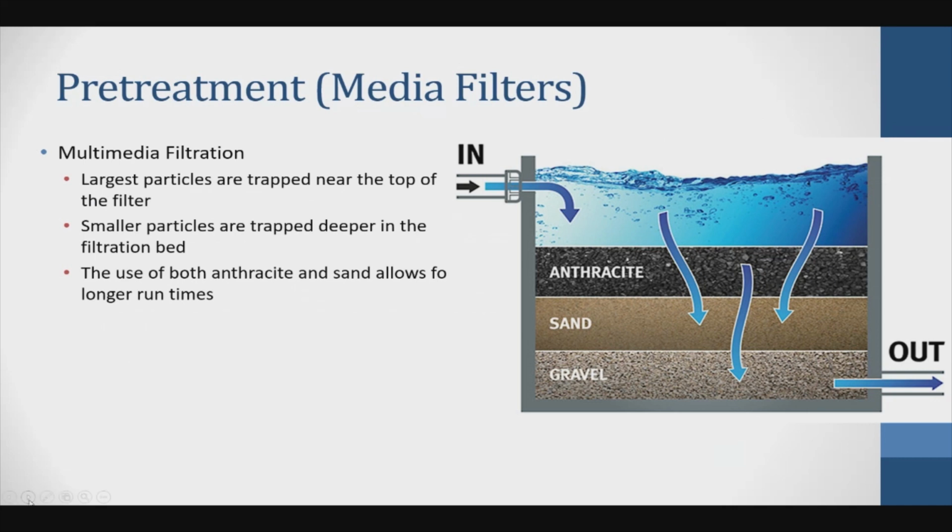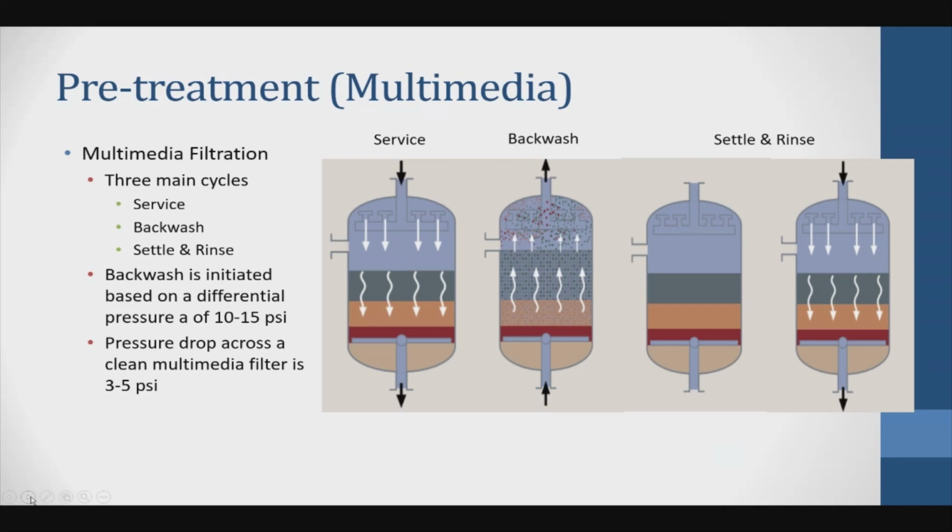All right. Now, these are the different cycles that we already talked about: service, backwash, settle, and rinse. The settle is a short period of time, like a few seconds, just to make sure that the automated valves go back to their location.